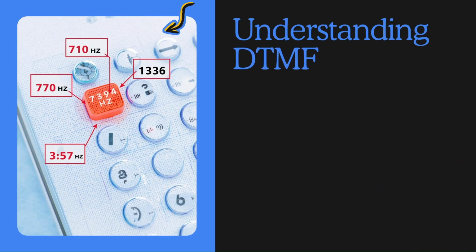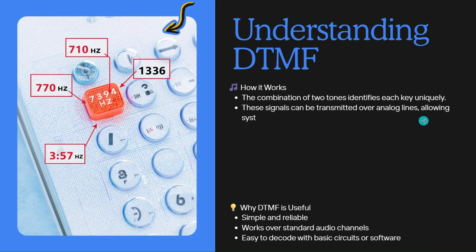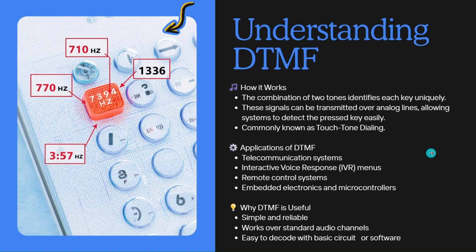These pairs of tones allow telephone switching systems, modems, or even microcontrollers to easily recognize which key was pressed, even over an analog audio line. That's why it's often called touch tone dialing. DTMF has been widely used in telecommunication systems, remote controls, IVR (interactive voice response) menus, and even embedded control systems because it's simple, reliable, and easy to decode with basic electronics or signal processing.